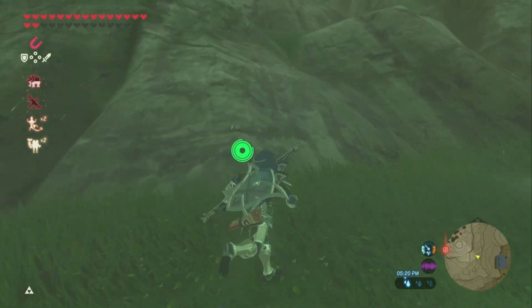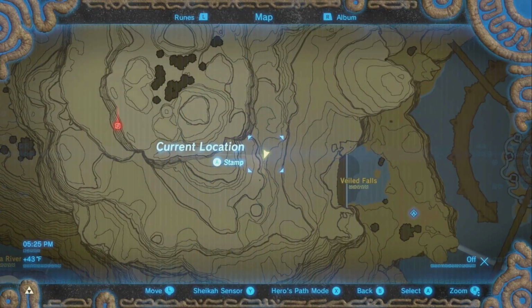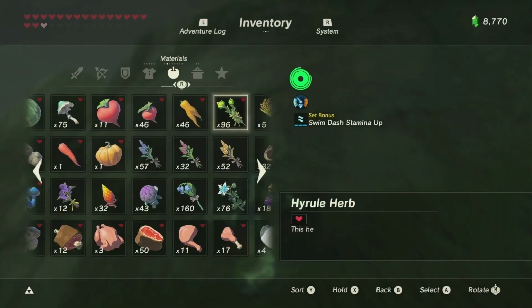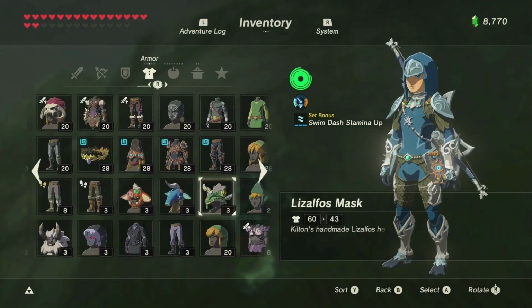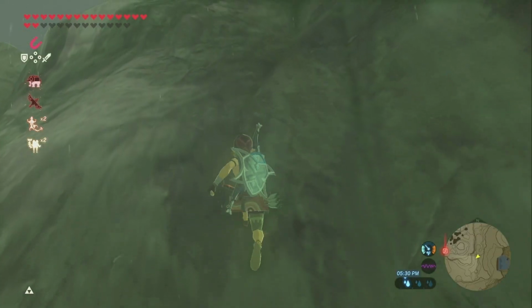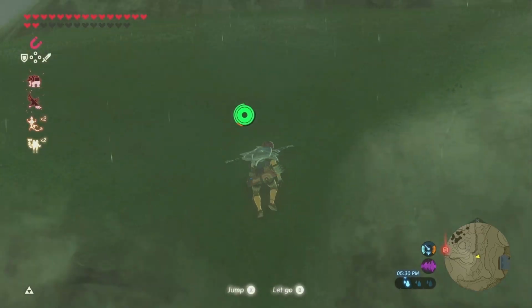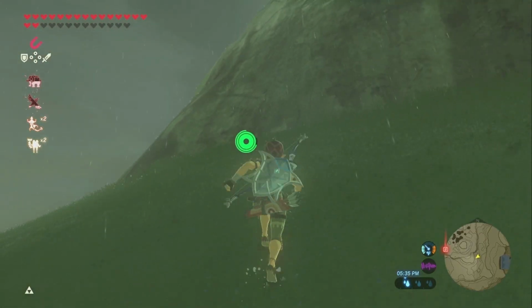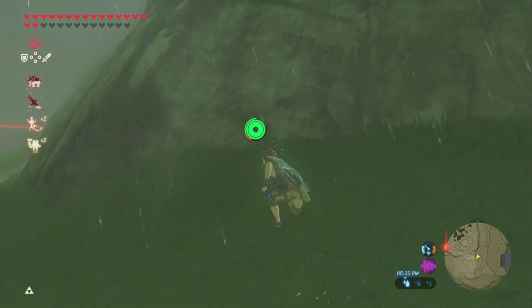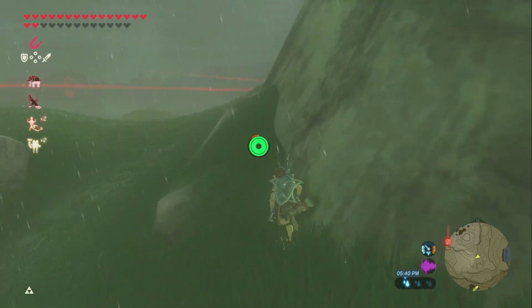Cause, say it with me now: this is an installation issue. Implications: if there is no isolating valve, the system can't be turned off in an emergency situation. Additional water damage may occur. Strategy: check that there is an isolating valve on the cold water piping adjacent to the water heater.